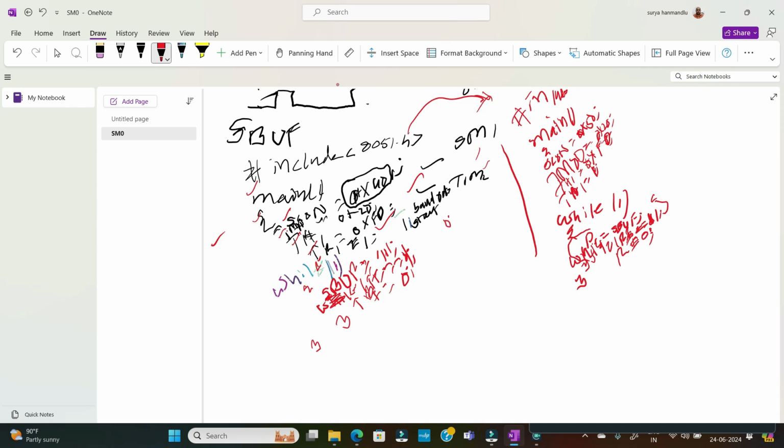If the timer starts, it starts from 00, then becomes 01, then 02, and it continues up to FF. Then the timer overflows to 00 again. All these concepts you can learn from timer modes of operation; a separate video is there in my playlist. Coming to the next, we have to open a while(1) loop, which is always true.